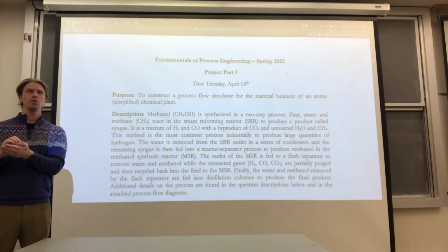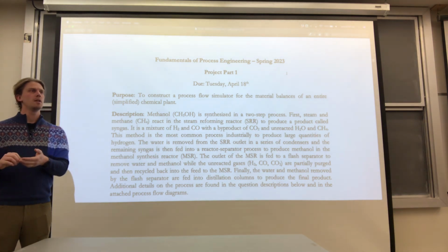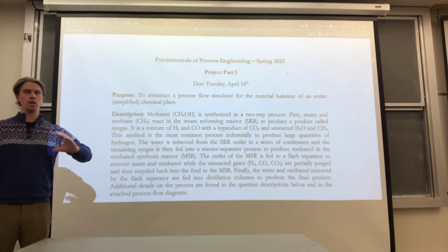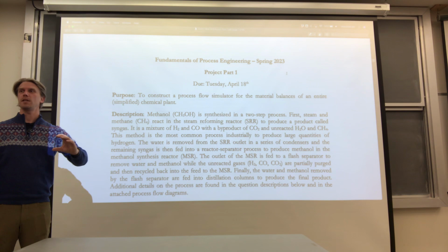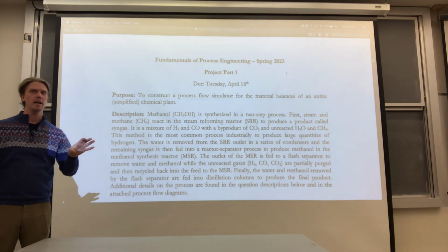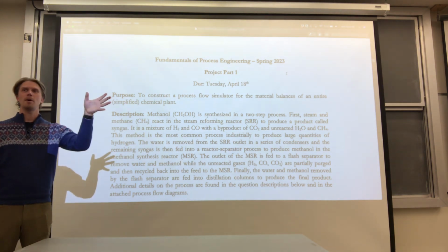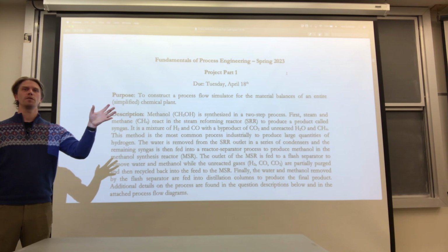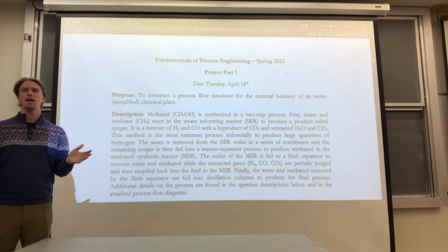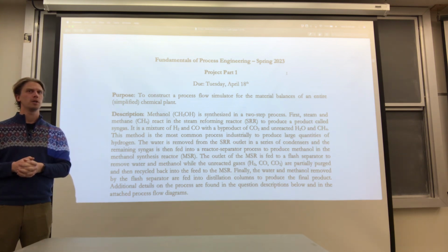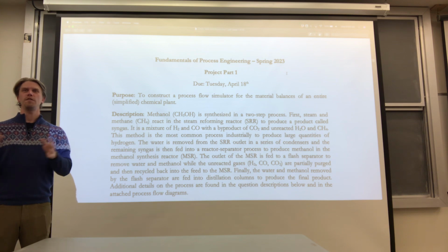But when it comes to a homework problem or the project, it's really just add another table below your material balance table with all the enthalpy values, right? And then it's just adding up all the enthalpies times their molar flow rates, and voila, we have our energy balance constructed. Does anyone feel quite like that yet?